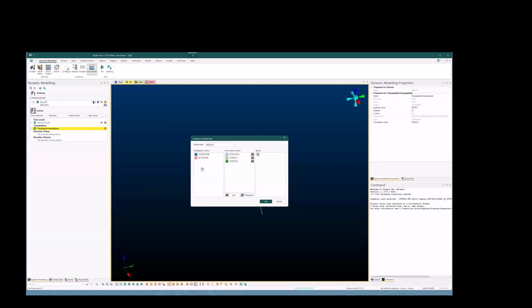So just in this window, you can see stratigraphic values and cross-cutting values. The difference between these is this is a contact surface, so basically a flat contact between 2 different units. A cross-cutting value is an intrusion. So the intrusions are going to have a hanging wall and a footwall point, and what it's going to do is create a wireframe in between these 2 points.